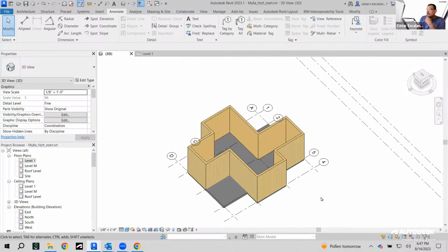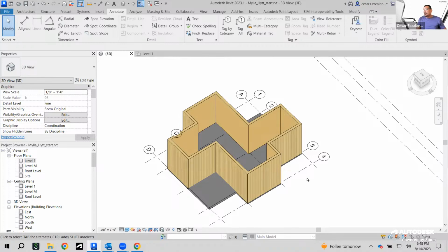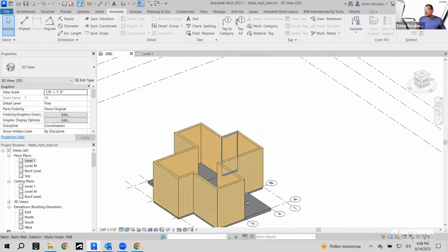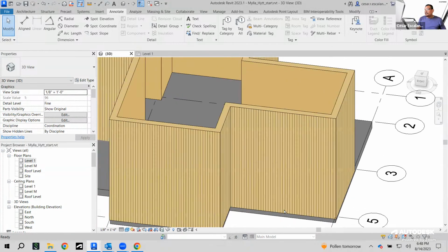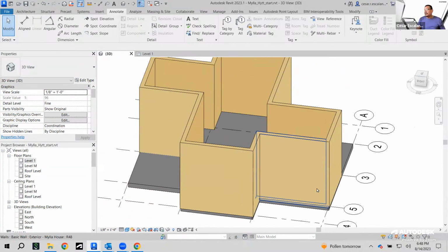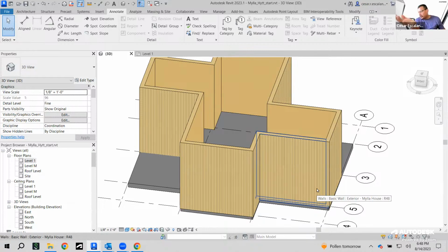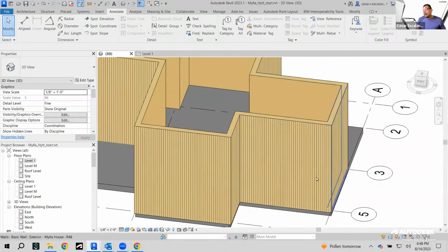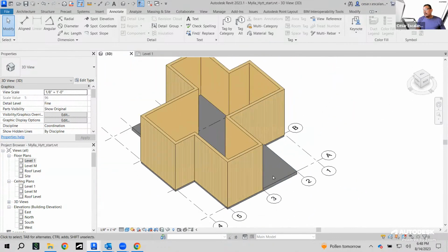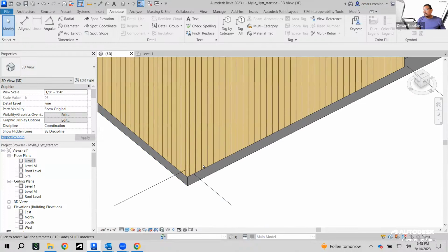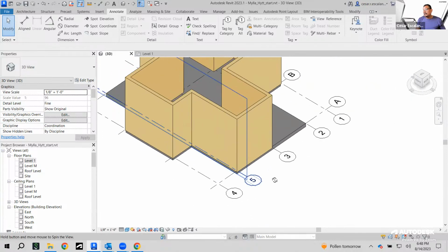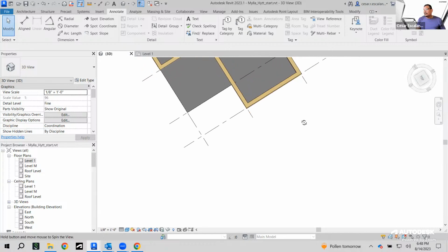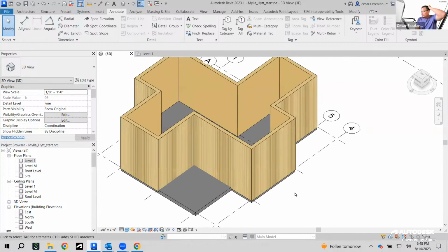Okay, so we have a chain of walls here. Any questions? And this was done completely from scratch. We started with the generic one. We added new layers. We assigned new materials. We created new materials from scratch. We built the exterior pattern. We unlocked the layer in a section definition. We applied the same distance to all of the walls. And so the next thing we're going to do is to slope the top.